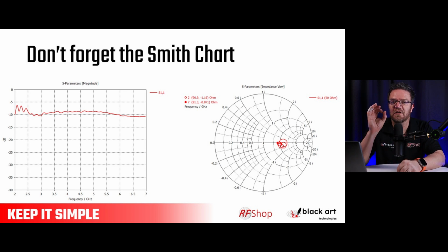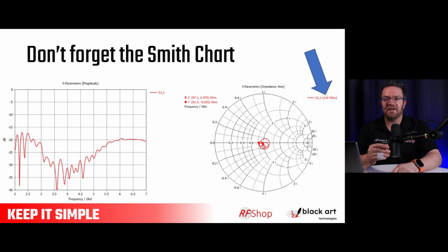And that's that the impedance locus is around 110 ohm. So it's not hovering around 50 ohm. If it was hovering around 50 ohm consistently, you'd need to think about something else to do. But this one shows the antenna is very consistent and stable. It's just at the wrong impedance. So what you do in software, first of all, before you do more design work, is change the relative impedance of your port that you're exciting with. That's all you do, and there are ways to translate that to something that you physically do as well. And the new value, which I can see there on the screen, is 110 ohm.